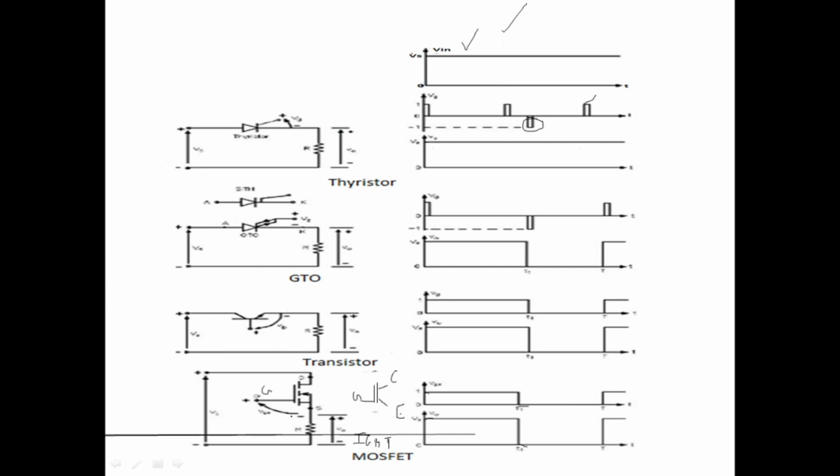In place of the MOSFET, you can connect it here. We apply a gate voltage between gate and emitter, and in the current path we connect using the collector and emitter. So the symbol uses parts of both the transistor symbol and the MOSFET symbol. The characteristics are also like that: the IGBT has the characteristics of the transistor as well as a few characteristics of the MOSFET.